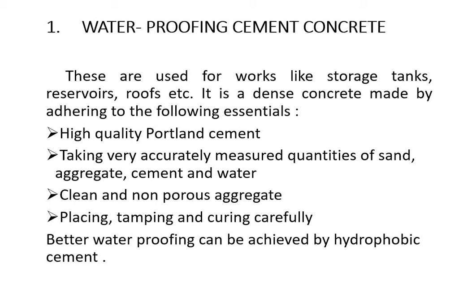High quality Portland cement must be used. Clean and non-porous aggregates must be used, and better waterproofing can be achieved if you replace this Portland cement with the help of hydrophobic cement.